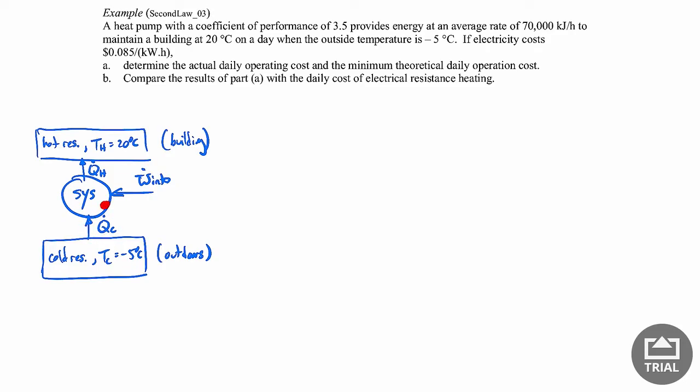Then we do some work on the refrigerant, move it around, do some processing on it, and then we can release the energy that's in the refrigerant into our hot reservoir. That's the Q dot H. Again, to get the heat transfer, we just need to make sure that the refrigerant with our energy now has a higher temperature than the hot reservoir so that we get some heat transfer there.